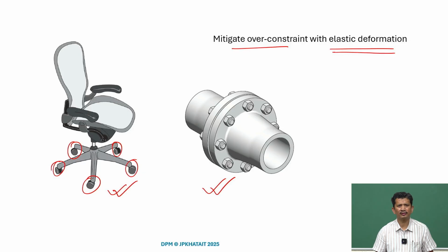Therefore, it is not desired, and we will see some examples where the location and the clamping can be achieved using exact constraint design. So, we may not have to worry about proper alignment, it will go to the same location all the time. If we create some features on the surfaces, then we can bolt it and secure the joints.